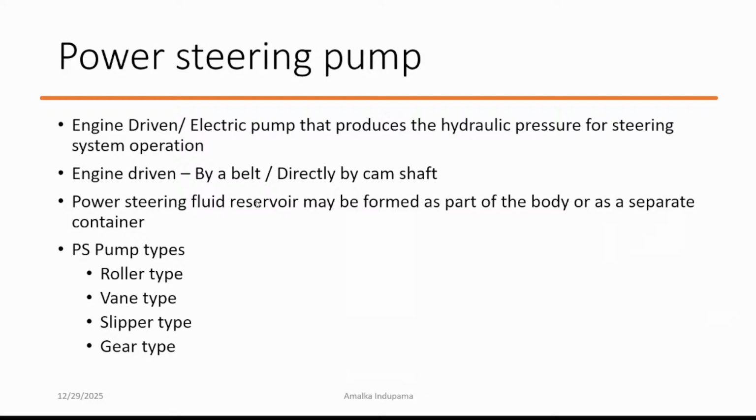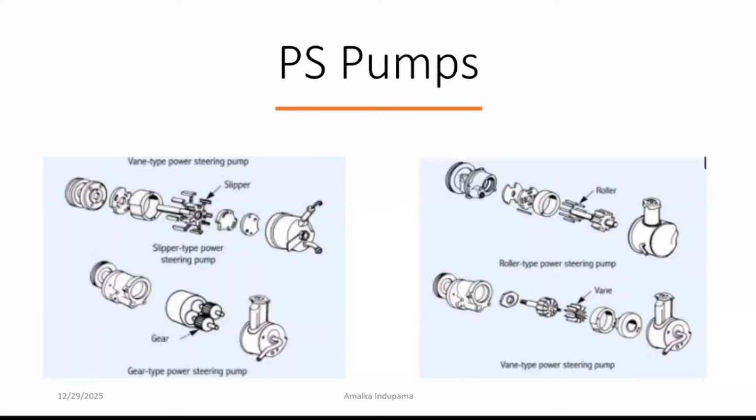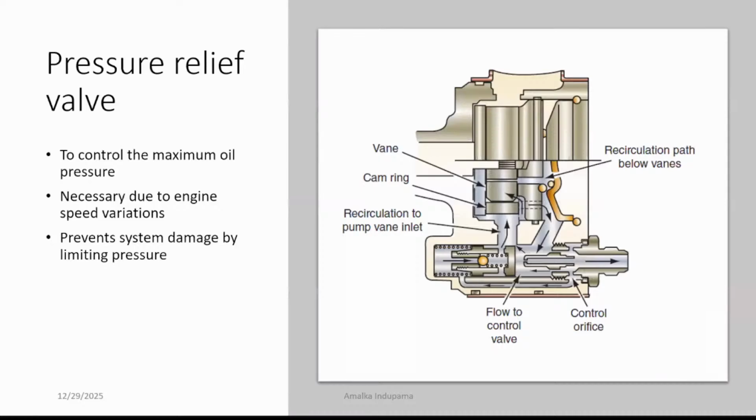The purpose of the power steering pump is to increase the pressure inside the system that actuates the double acting cylinder, right? The pump outlet is connected to the pressure relief valve, which is a kind of pressure regulator.